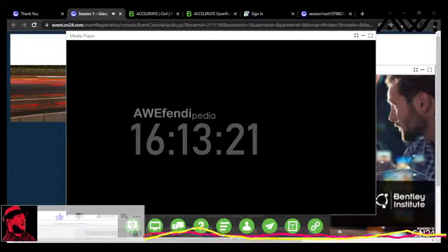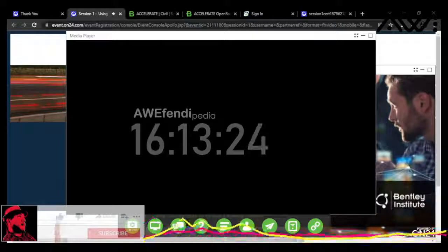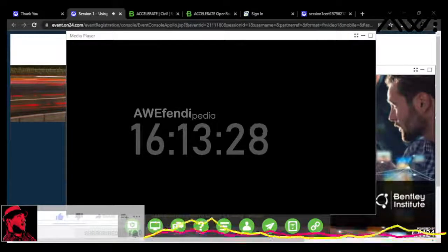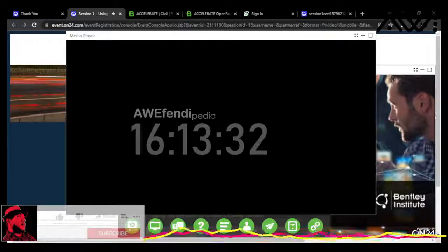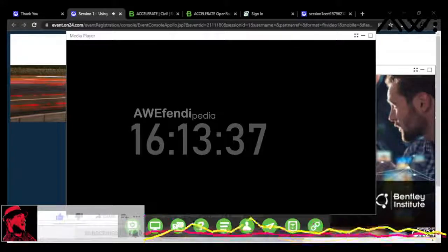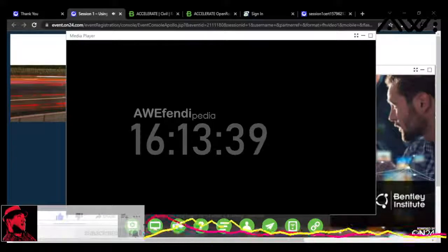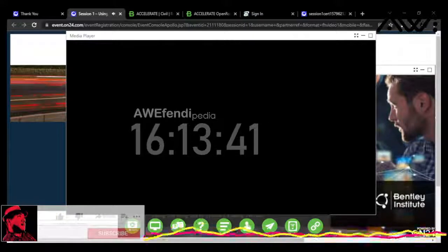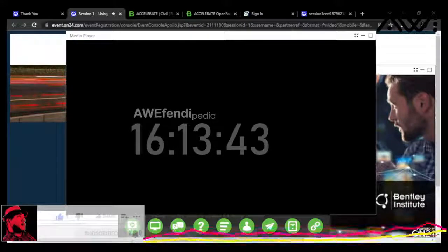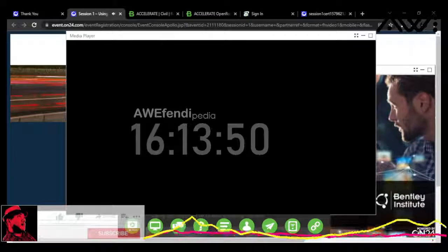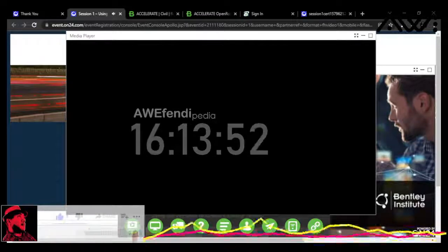Well, at the same time he was collecting this other driveway, and he called this point DW, and he called this point DW1. You see that again in that field code line, which is the second line in our tooltip. So it looks like instead we wanted to connect up a driveway coming down on this side. And if I look, there are 2 points here that aren't connected to anything, and those are DW and DW1. So I can see it's just a matter of we've gotten the string numbers mixed up between the two driveways.